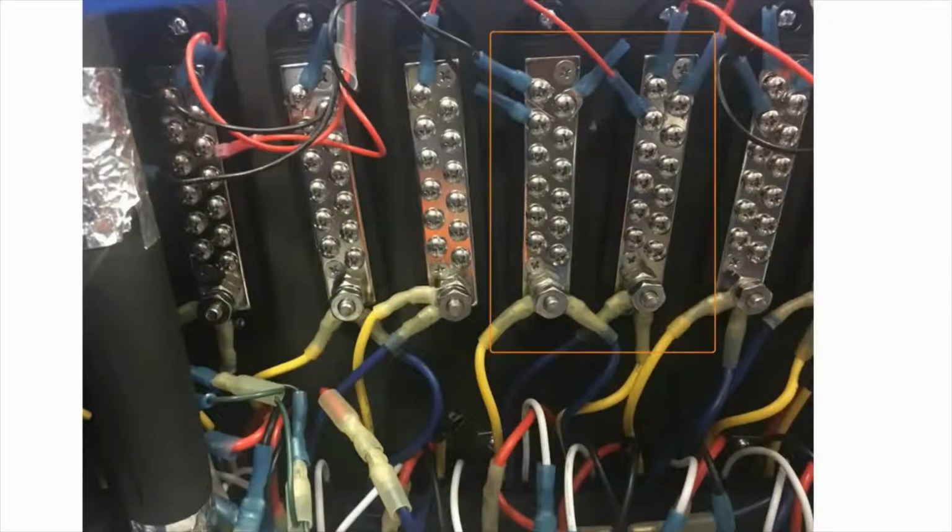These 2 bus bars are a single array used to control the mode of our Peltiers. The Peltiers are split up into 4 arrays. 3 of the arrays have 3 Peltiers each, while the final array only has 1 Peltier. The mode is controlled by the relays below that allow the current to flow from either yellow to blue or blue to yellow. This creates a situation where both sides of the Peltiers can be either heating or cooling.